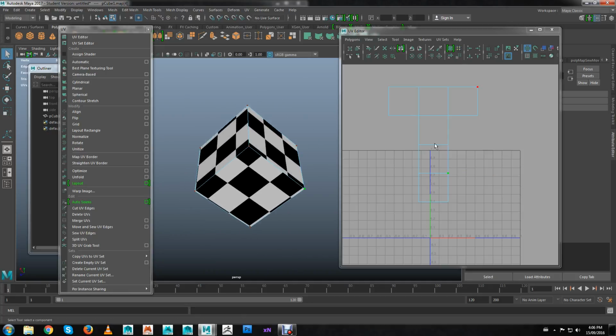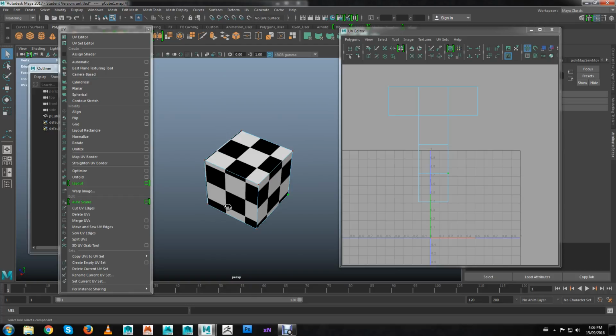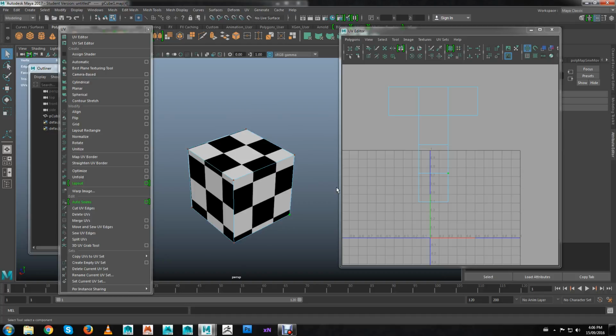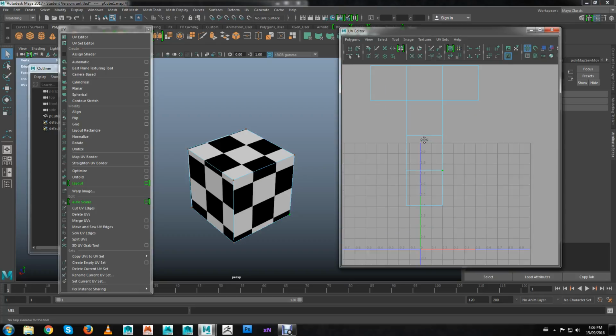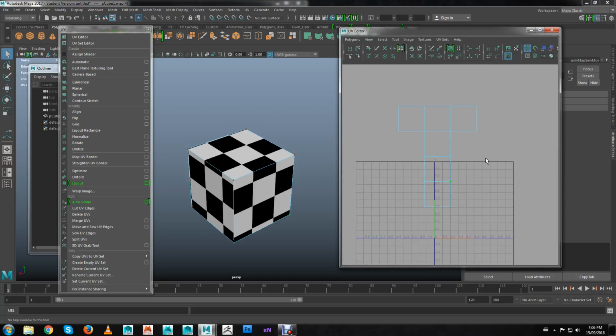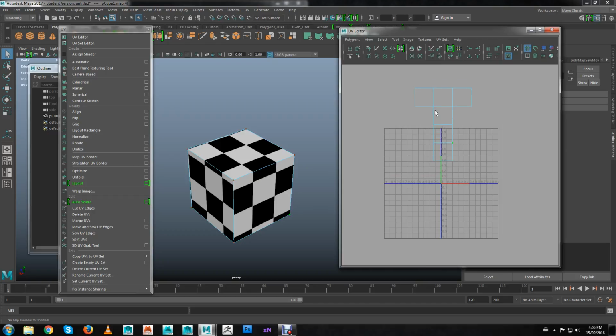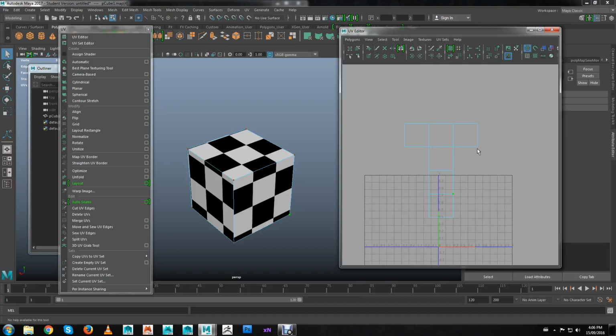Okay, so there's a look at UV shells, what they are, how to make a projection from all sides of an object, a very simple object, mind you, and then arrange your shells back together, sew them. Okay. Now there's one more thing I want to cover, which is arranging the UVs in the proper UV space, coordinate space. So we have our UVs sewn back together here, and because they're all sewn together, this is one UV shell.